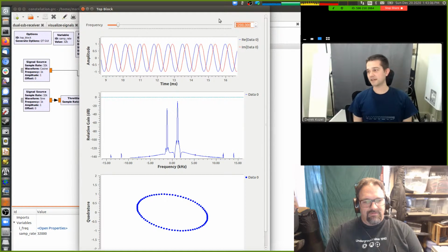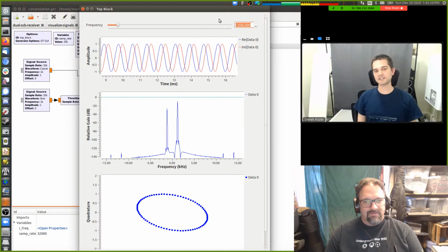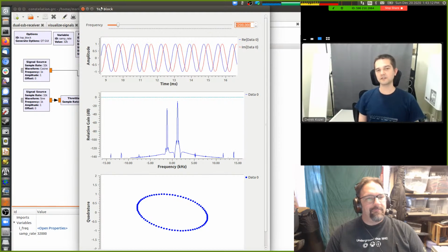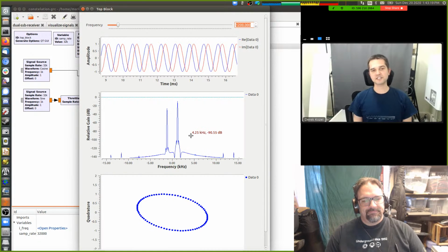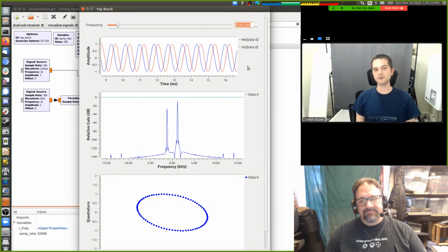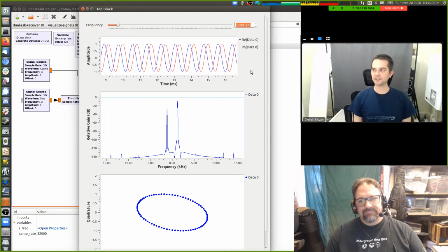Interestingly, as a bonus round for people here, you can see that we're now getting a positive and negative signal when we're only expecting there to be a positive. What we're actually seeing is a phase discrepancy between the I and Q. This is why you get IQ images and why some SDRs offer IQ calibration.